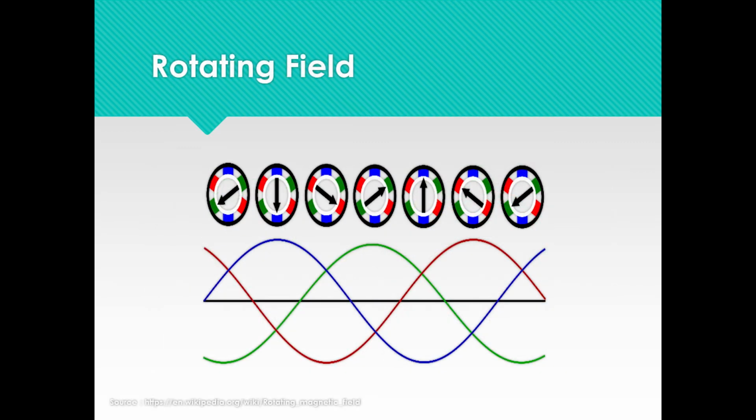In this picture, three-phase voltage is shown by the time. As I said before, the sum of the three-coil magnetic fields is a rotational field. It has a fixed peak magnitude and a frequency of the power system, 50 or 60 Hz. In these circles shown above, you can see the rotational magnetic field as a black arrow in different times.